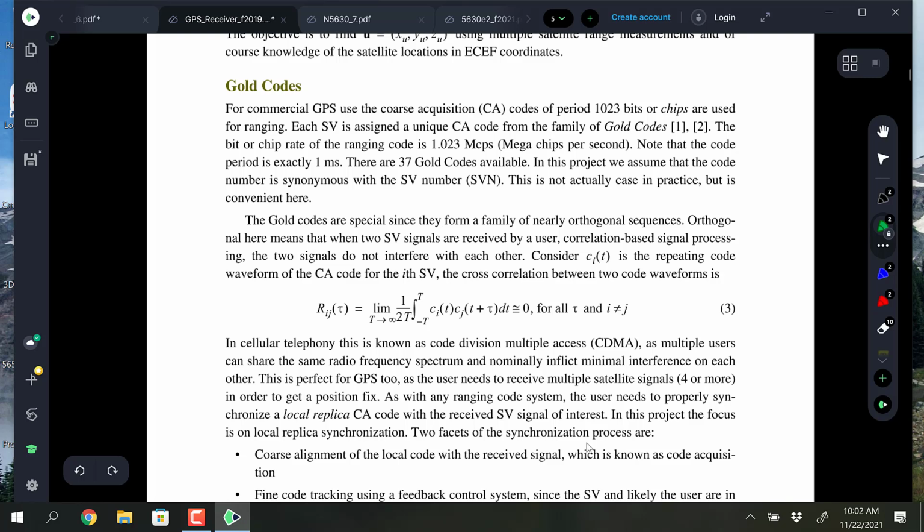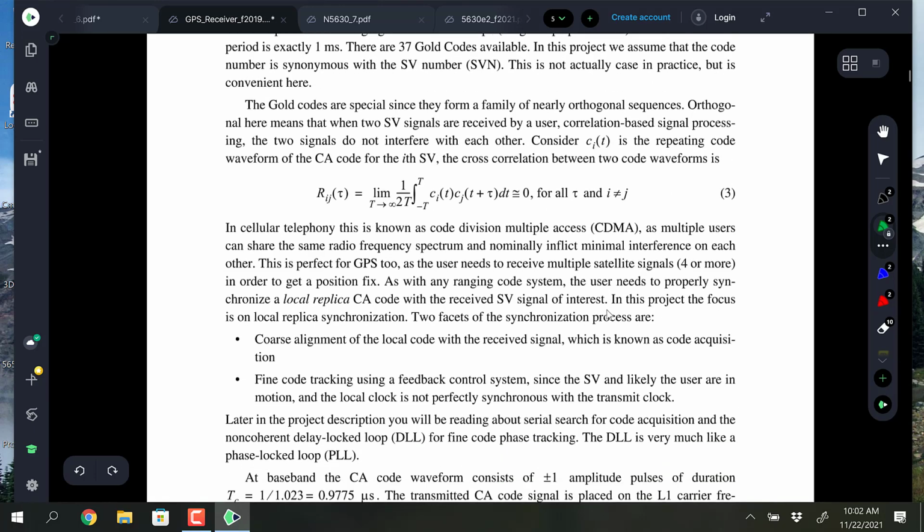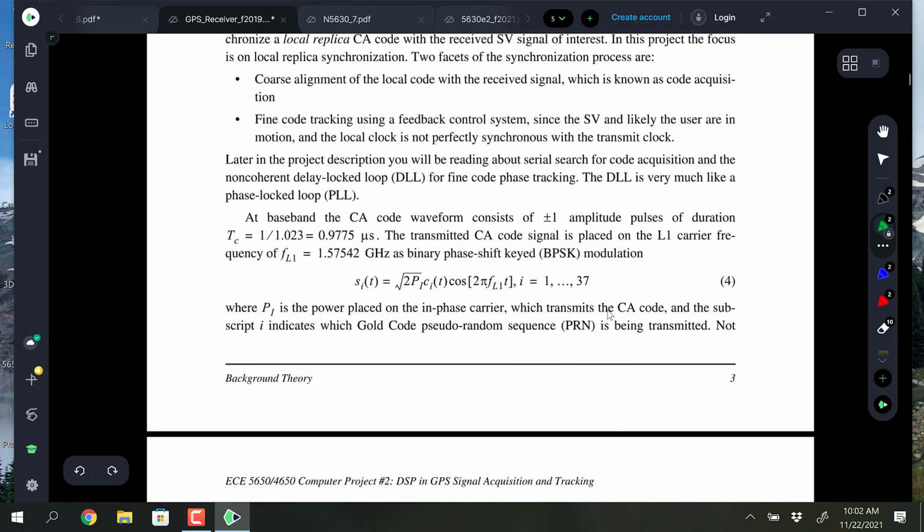So this talked about gold codes and how we're going to correlate a received code with a local code, and we have to pick the right code because we don't know what satellites are visible. But the data stream that comes across on the GPS, this 50 bits per second, sends the ephemeris data live from the satellite. So you get to know where the satellites claim that they're at right now in time, and then you can use that to make the tracking converge faster.